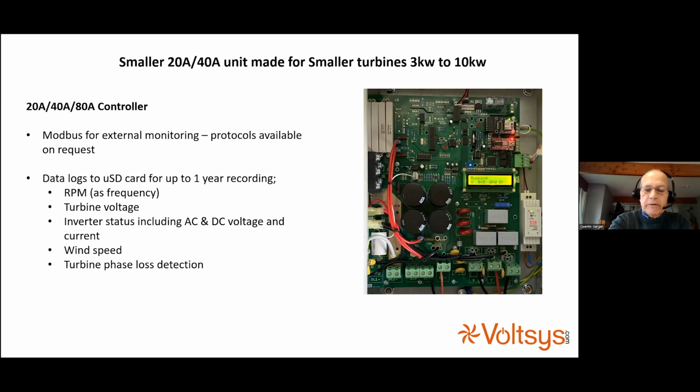But if you lose one of the two phases that you're not measuring from, the turbine will then continue to be loaded by the inverter, and it will cause a lot of vibration and could do damage. So phase loss detection is quite an important feature.